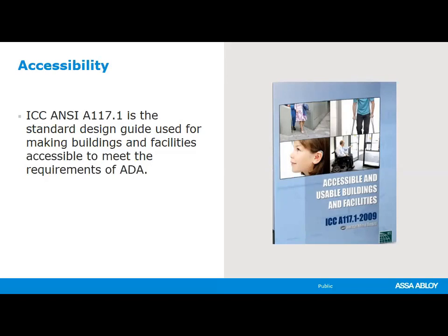Please know that there are other state accessibility codes. They may conflict with what ADA requires, but ADA is a minimum. If your state accessibility code exceeds that, then certainly follow your state accessibility code. But ADA is a minimum. If your state accessibility code goes under what ADA requires, you still need to follow what ADA requires.